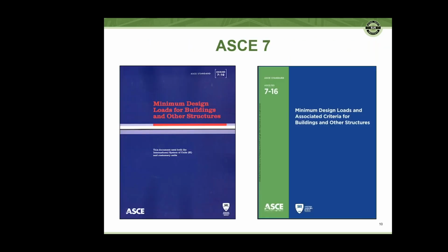Other important documents that are reference materials for specifying steel joists would be ASCE 7. And most projects these days are working with ASCE 7-10. ASCE 7-16 has been published and will be coming into force as IBC 2018 gets adopted, and Keith will touch on a couple things later relative to that. We still see a few projects come through that are making reference to ASCE 7-05. But I think it's time to move on from that one, and again, there's a new one coming up.